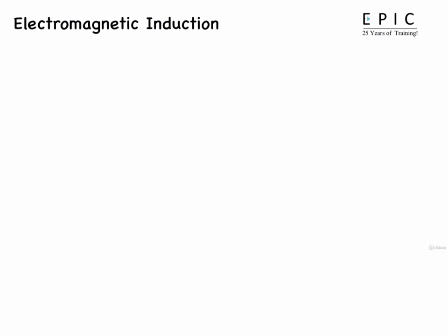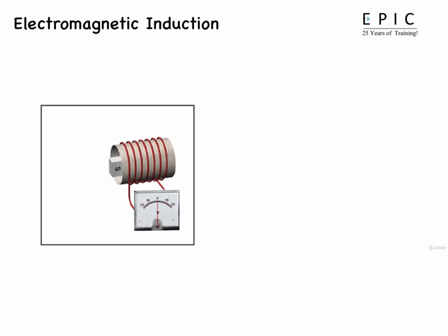Our modern world would be impossible without electromagnetic induction, the phenomenon that underlies the operation of many devices, including transformers. Qualitatively, here is how electromagnetic induction works. As the lines of flux cut across a coil or coils of wire, the number of magnetic lines of flux cutting the coil will be increasing or decreasing. As it increases and decreases, a voltage will be induced in the coils.